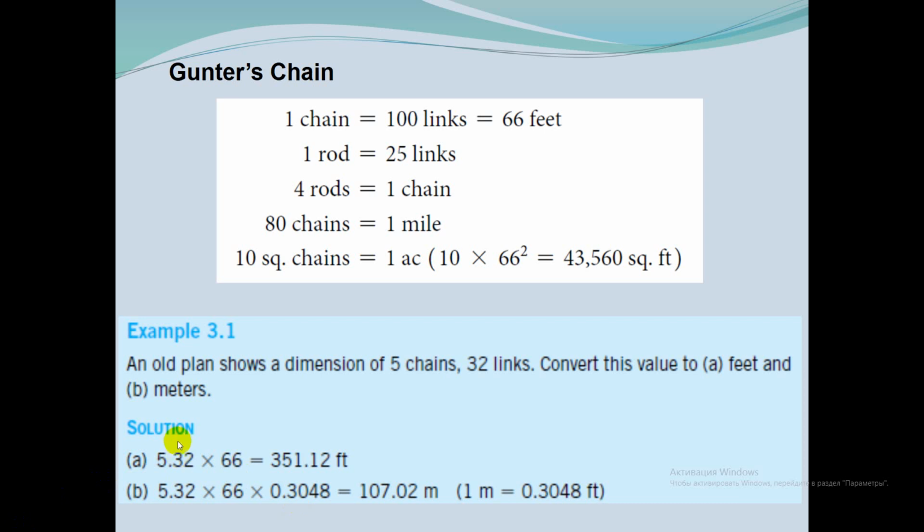How to determine this? You know that one chain is 66 feet. So 5.32 multiplied by 66 equals 351.12 feet.